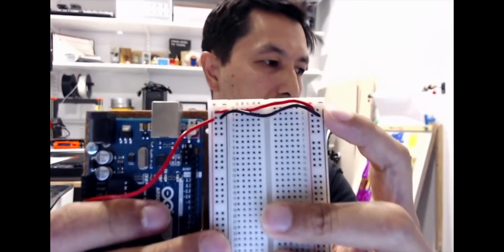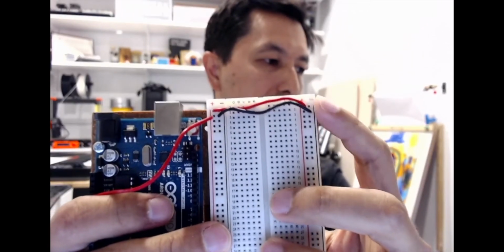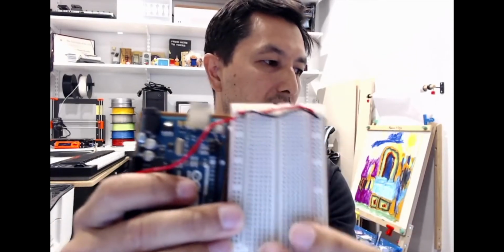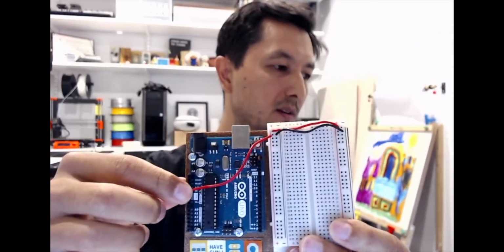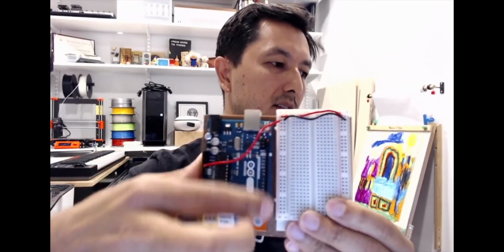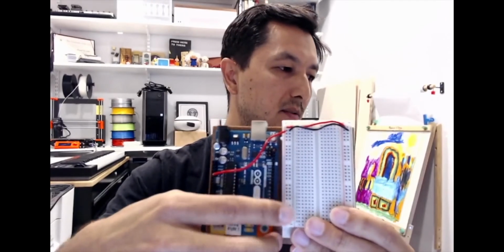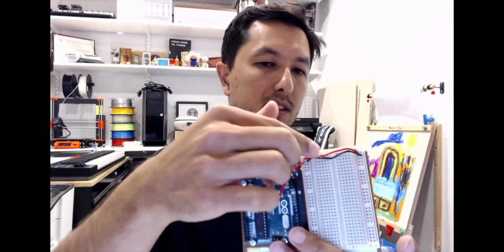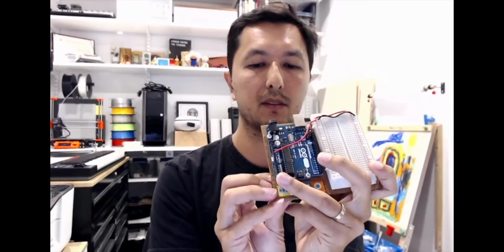Okay, so I normally do something like this with my breadboard. I attach the positive sides together with a red piece of wire here, and then I attach the negative sides together. Then when I attach my voltage from either the battery or the Arduino to any one of these rails, and also the ground side, which is black, back to the Arduino, this rail will get power and this rail will get power every time I plug it into the Arduino. So that's why it's connected here. I can use either side for power and ground, essentially. That's just a good technique when setting up your breadboard.